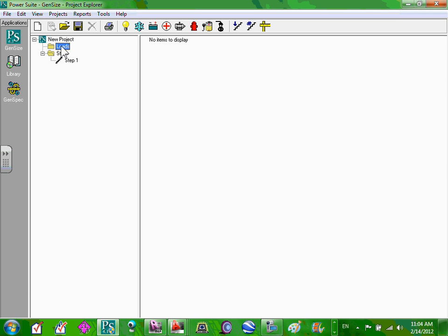Steps, you're going to add a step, meaning you're going to start these loads at the same time. If you put all the loads in one step, you're telling the software that you want all these loads to start at once. That's the worst scenario for any generator. You want to split them into steps. But the problem, I want to remind you guys, the riser that we have, remember the riser that we have?